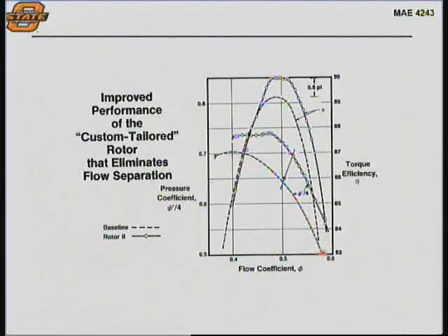As I described before, how you make a compressor map: this is for one stage, and you would control the power into the rotor with some measured electric motor. So you're controlling the power into the compressor stage, and you have a throttle that governs the mass flow through the machine. You fix an RPM, in this case for this baseline design, and you slowly close the throttle.